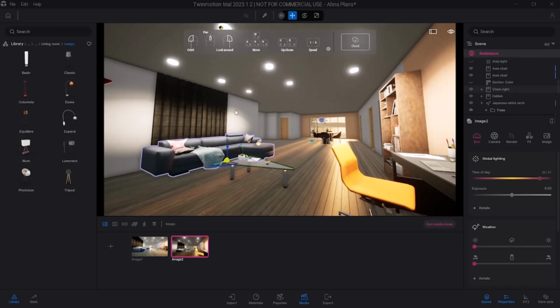Currently, remember that we don't have access to ray tracing, so if I hover my mouse here, you can see that my laptop doesn't actually meet the requirements for the Path Tracer feature, so we have to work with normal lighting systems in this case. And going into the lighting exposure, you can actually reduce the exposure to about 0.5 and see what, oh, that's an increment, sorry, minus 0.5. And okay, this is what we get, so that's a bit too low from what I enjoy doing, so minus 0.25. Yeah, we can leave it at that.